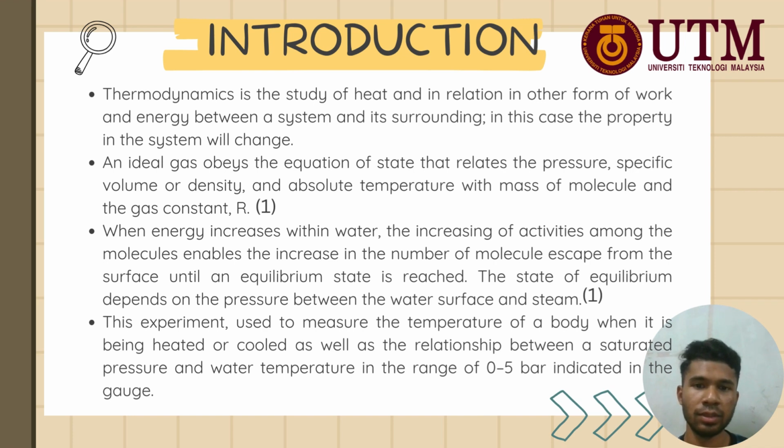When energy increases within water, the increasing activity among the molecules enables an increase in the number of molecules escaping from the surface until an equilibrium state is reached. The state of equilibrium depends on the pressure between the water surface and steam. This experiment is used to measure the temperature of a body when it is being heated or cooled, as well as the relationship between saturated pressure and water temperature in the range of 0 to 5 bar.